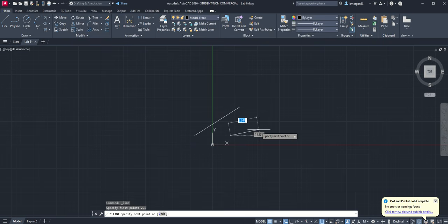So here is your first point, and we don't want to measure from the 0. The 0 is this guy. If you go with a pound, your measurement will go from this. Right now you want to measure from the first point 2, 1, which means a relative Cartesian coordinate that we want to do. So how do we do that? We will just use a code, the at mark, so your application understands: oh, we want to do relative, and we want this 2, 1 as a reference point. My reference point is not this.